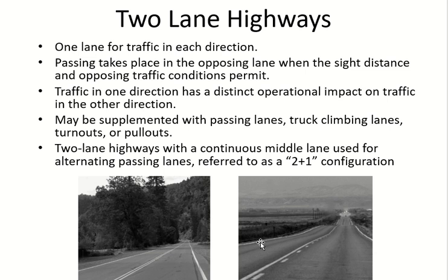Then you can have a temporary extra lane for turning movements. You want to pull out, go out of the highway. So there's a short lane for you. You go into that lane and then you make the turn because you will be slower. Same thing if somebody is entering the highway from a street. There will be a short lane for them. They will enter into that lane and then come to the highway to control their speed, to avoid the risk of slow drivers on the highway. So this is called a turnout. Turnout is when you're coming in, pull out is when you're going out.